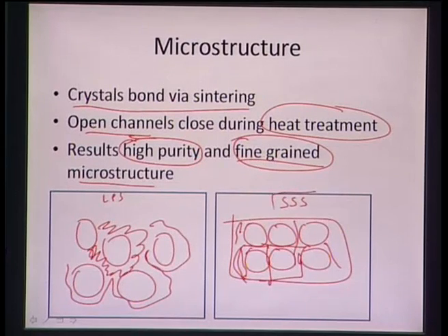So in this case of solid state sintering, we will see all the particles which have come closer, and also they will have some sort of surface melting because of the surface contours, the curvature. Surface can melt to a certain extent, but it will be very marginal, and then it will contact the nearby particle, and then volume diffusion and surface diffusion will create the bond with the nearby particles. But solid state sintering cannot eliminate all the porosity, because we need very high pressures at very high temperatures to eliminate that porosity.